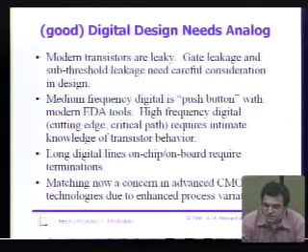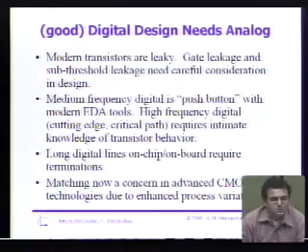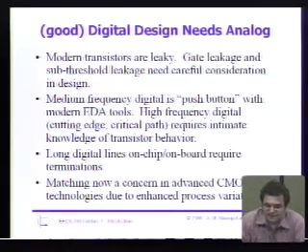Well, good digital designers definitely need to know some analog. One of the reasons is that, classically, the model of the transistor a digital designer uses is the switch model. In other words, they say a transistor is a switch. It's either on or it's off, right? If you look at a modern transistor, you need something a little more sophisticated. It's basically hard to turn off that transistor. It likes to leak. The gate is leaky because you use a thin oxide, and the drain is leaky because you're going to have subthreshold conduction, and that's going to impact your design.